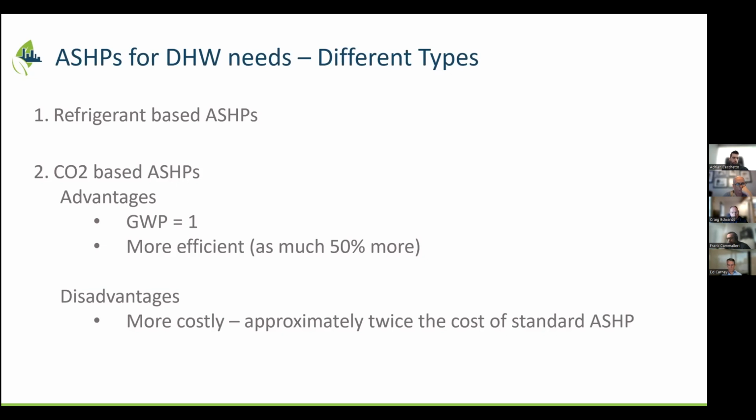Okay, at least with domestic water. Domestic water, yes. That's a hot topic, and thanks for touching upon that, distinguishing the requirements of a local need. So obviously the local infrastructure that disconnects the wiring going to these domestic hot water pieces of equipment is going to be higher because it was natural gas fired, with very low electrical requirements. So you're going to need that. However, typically, given the sizing of domestic hot water needs relative to the infrastructure and the main feed coming to the building, you're not seeing these as the trigger where you have to upgrade your main electrical service. The other items we'll talk about afterwards tend to lead to that, but this is one safe area where it doesn't usually force you into a major electrical infrastructure upgrade to the building.